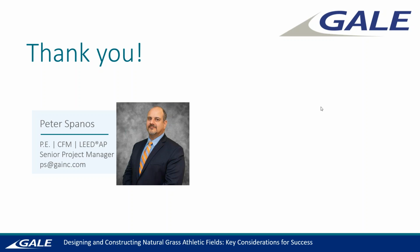Sorry, I was muted. So yes, for the baseball and softball field in Florida, fortunately, Florida has a little bit better free draining soils. Their problem was their planarity and their overall growth issue. So they chose to go with their native soil. They tested it, amended it with some additional sands and some more organics, and placed that back down.